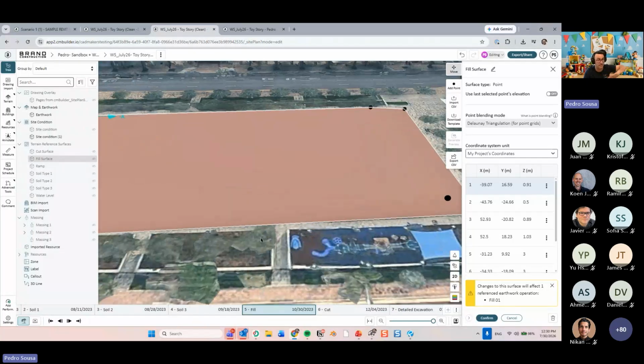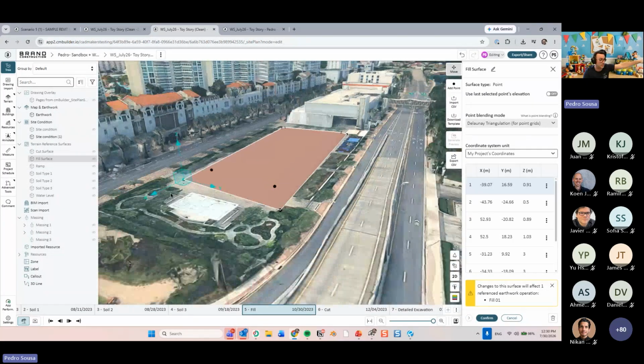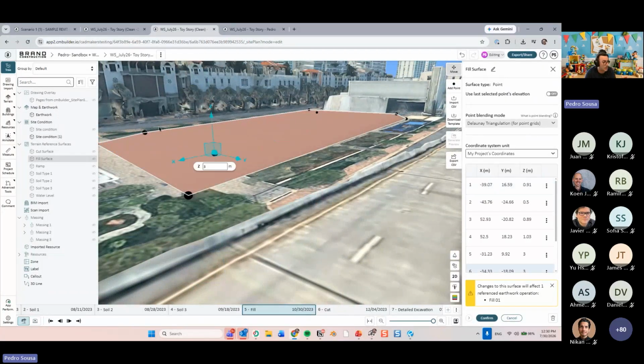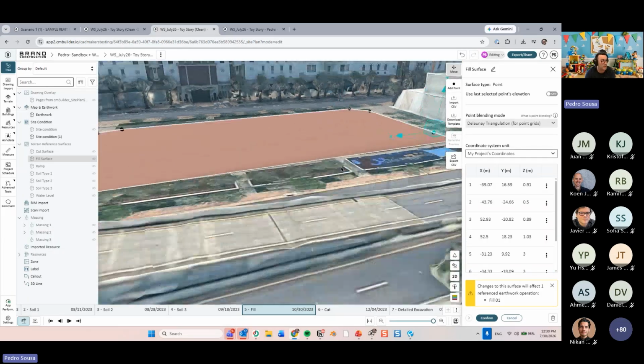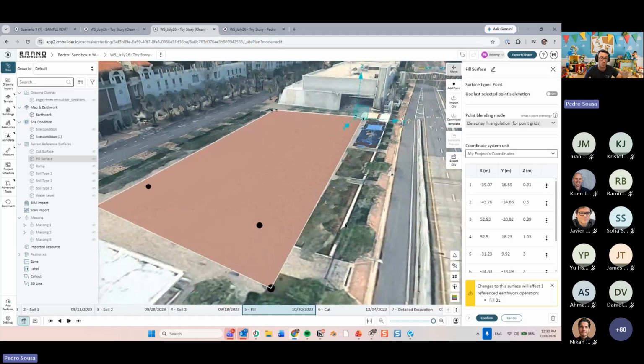On where I want my fill, my slope, to end, like points over here, these four corners, and then points on the top that will have different elevations if I want to, like say these are all three elevations to create a flat top over there, but I could have the fill with a slope and whatnot. And then you control where the fill's slopes will stop and where the flat part of it will also be limited, and so on and so forth, right?